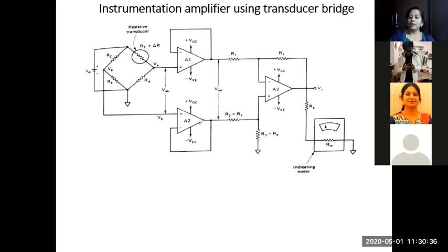If I don't use this voltage follower, the signal VAB will be much reduced by the circuitry by the time it gets connected directly to this difference stage, the second stage. So if I want to avoid that, for impedance matching, as you told, this voltage follower stage should be used, and it also gives a very high input impedance to this instrumentation amplifier.